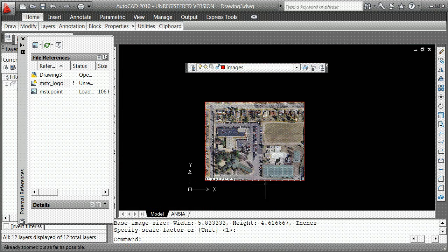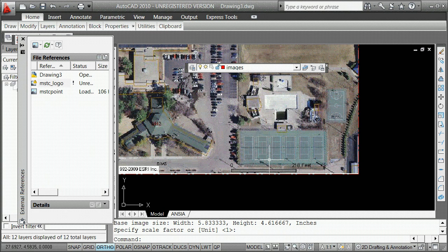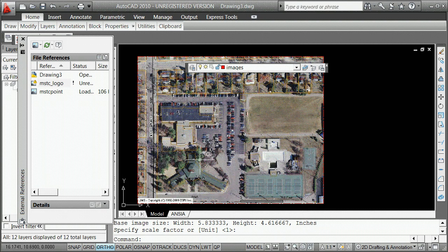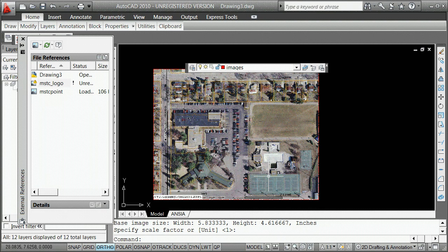It might be a section line or 2 section corners, because when you talk about relative scale, I'm going to also point out when you bring in aerial photographs, you want to make sure that you check the scale in both the north, south, and the east, west. As you're dealing with GIS data, it should be correct, but very often because of something called projections, the length of 1 degree latitude and 1 degree longitude is not the same here, so the scale might be off in the north, south, and east, west direction.